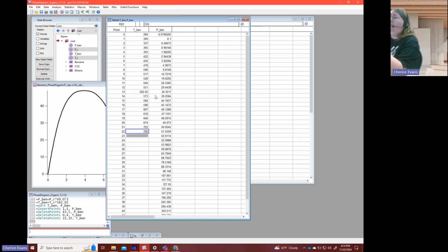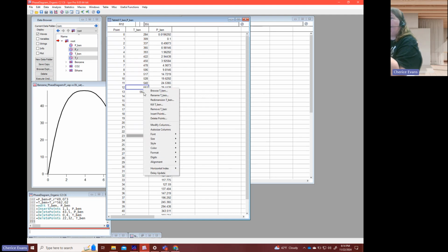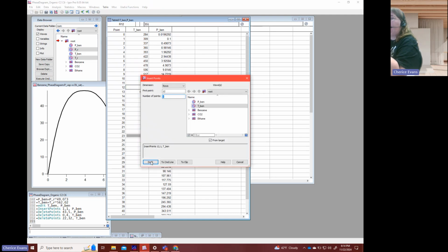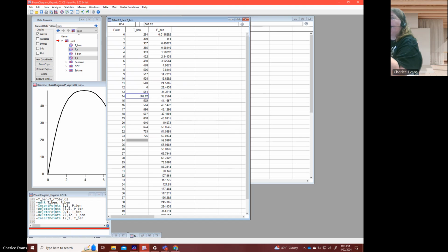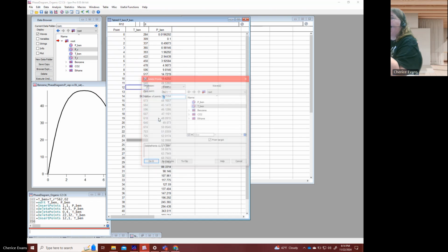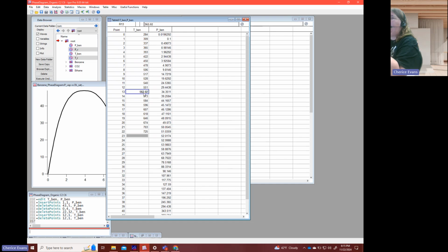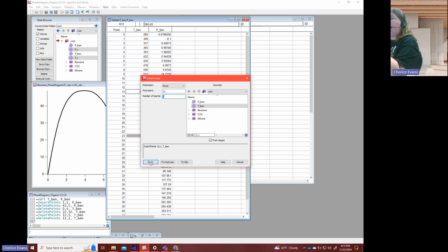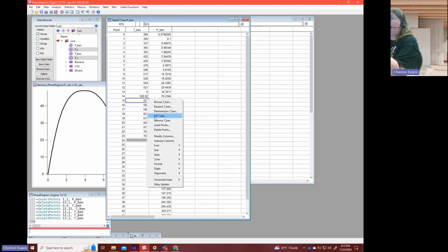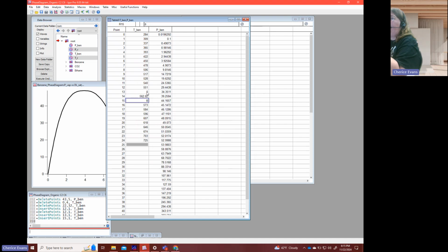Now, the other thing I know is 562 is the critical isotherm, and the area of biggest change is going to be right here. And right now I have a 10-degree difference in my isotherms here, and that was a 0.02 step, but I think I'm going to need to put at least one isotherm there. Oops, not there. I think I'm going to need to put an isotherm on each side of this because I think the step is too broad.